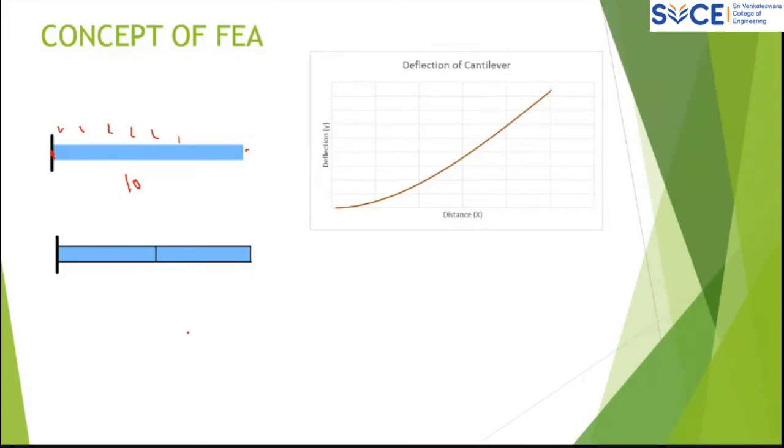When I solve it in FEA, I will get something like this. This curve is the pure analytical solution, right? Now I use a mathematical or matrix term. I am splitting into two, which means I got two lines, with one point and another point. You can see there is an error here; the accuracy is not the same. That is why we say finite element is an approximate method, right?